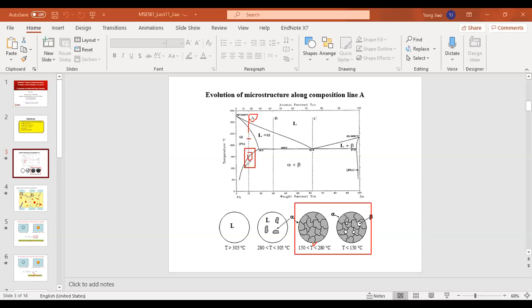And then we analyzed this when we first introduced the phase diagram. So if at this low composition you just go through the alpha and beta solidus, you're going to see the beta phase nucleate in the alpha phase field, and they start to grow. Okay, so this is very much like a nucleation and growth process, but you're not nucleating a solid in a liquid. You're nucleating a different solid, the beta phase, in the alpha phase field. You're nucleating a solid in a solid.